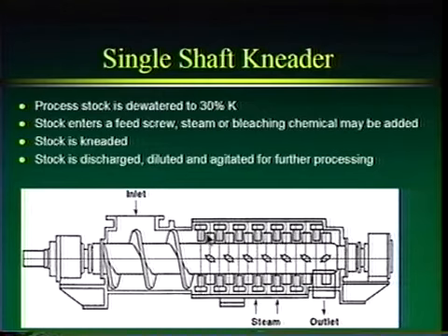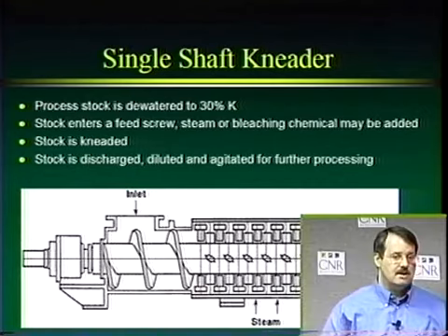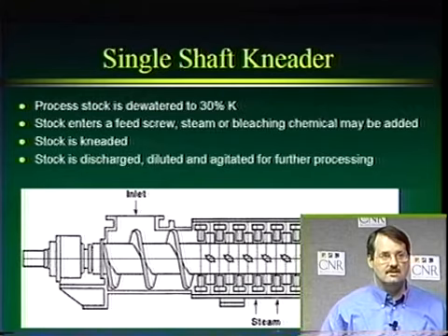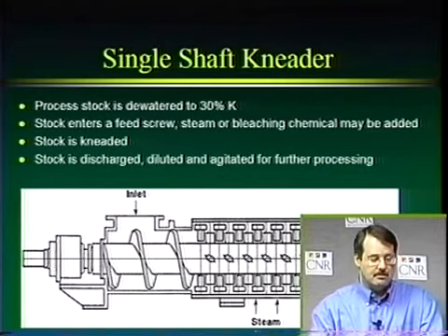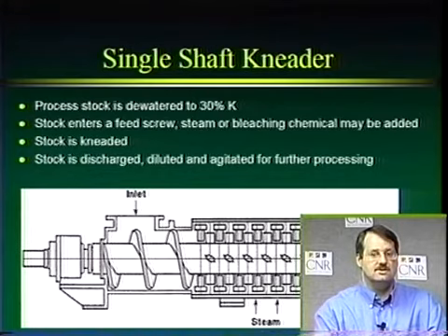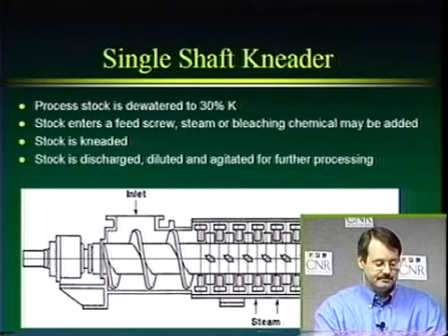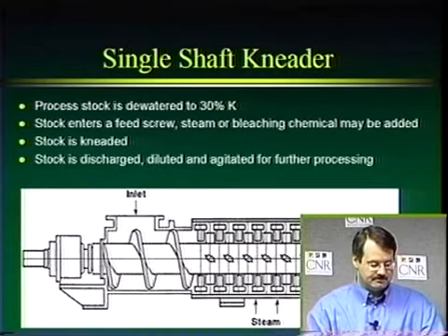And the fiber rubbing that occurs is actually breaking the contaminants. That's an important point. It's the fiber rubbing, not the metal to contaminant. In kneading, fiber rubbing does the breaking. In disc dispersion, metal teeth contacting contaminants does the breaking. So here we're getting fiber rubbing. That's why, with my analogy of the massage, what we're getting is a much slower, softer, gentler mechanical action as opposed to the disc disperser. Okay.